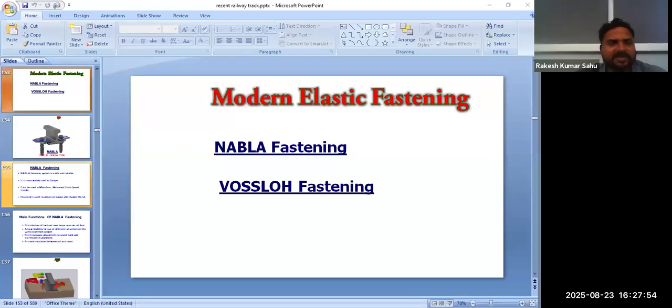So the main important function of ballast is to resist vertical, lateral and longitudinal forces, provide elasticity and riding comfort, absorb energy, reduce formation pressure, to facilitate track geometry correction, also provide track drainage, provide voids for better drainage, level and hard bed for sleeper, and transfer and distribute the load along with lateral and longitudinal stability and maintain the level and alignment. It also inhibits vegetation growth, absorbs airborne noises, and provides adequate electrical resistance.